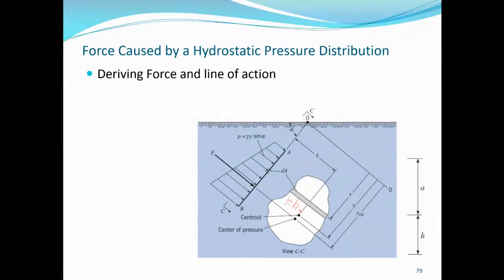As I mentioned to you, if it is inclined or vertical, then center of pressure and centroid do not coincide. They coincide only if the plane or the plate is horizontal. If it is horizontal, then you have uniform pressure distribution acting. If it is vertical or inclined, the pressure distribution is not uniform, meaning it is not the same at every point on the surface area. That is why you can see it is increasing. It increases as you go deeper down, because pressure increases with depth.